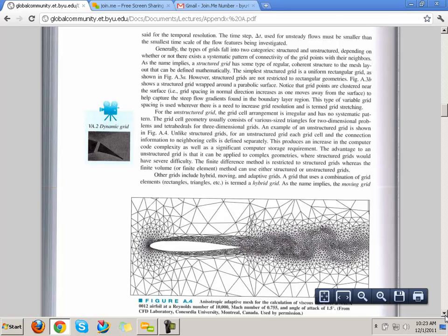And I believe, this is a small thing, but the boundary layer, which would be right around the edge of this object, is usually rectangles. If you zoom into your CFD that you're doing, you should see rectangles, I think. And then once you leave the boundary layer and it goes into the mesh, it'll just mesh the rest with triangles.